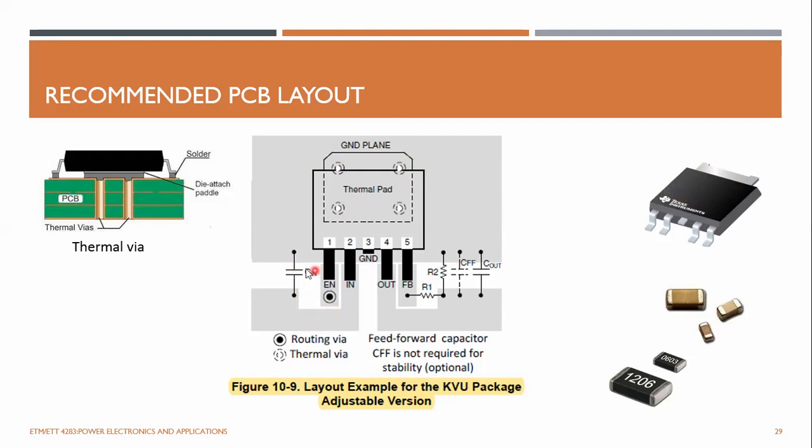And so you have seen these input and output capacitors. They should be very close to the device. You can't keep this input capacitor somewhere here, right? If you do, it will degrade the performance. And also you have to keep your output capacitor very close to the device output pin.